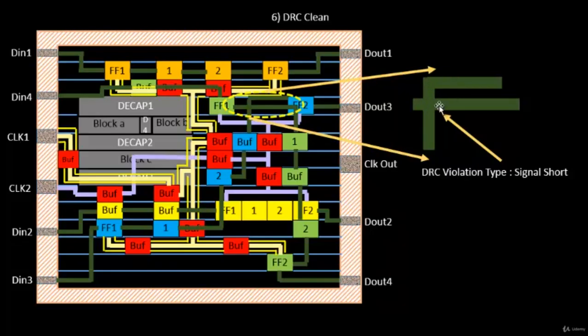The signal short is one of the rules. Apart from that, the remaining 3 rules will still be maintained between these two wires: the wire width, the wire spacing, and the wire pitch. So let's quickly see how we solve the problem of signal short.